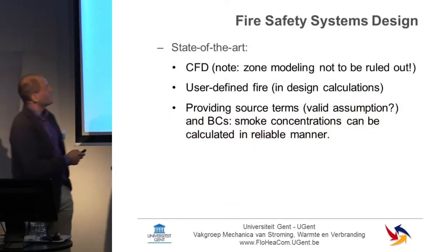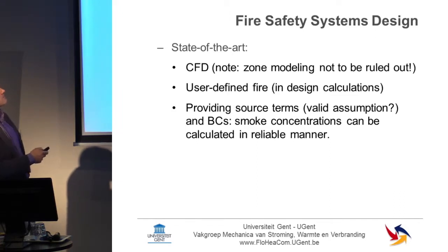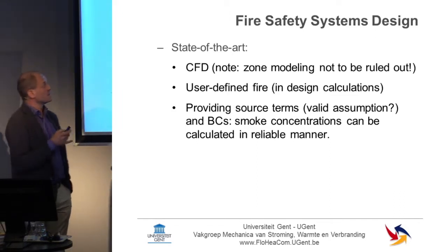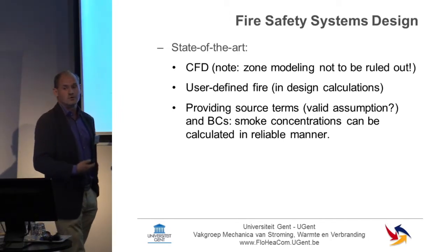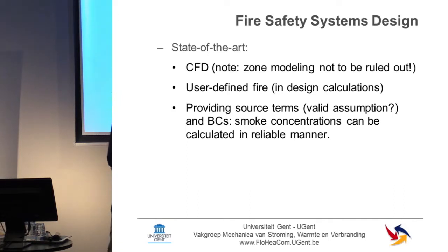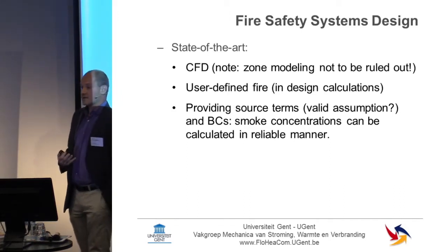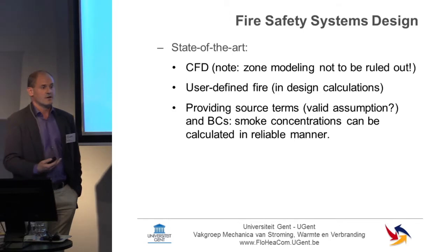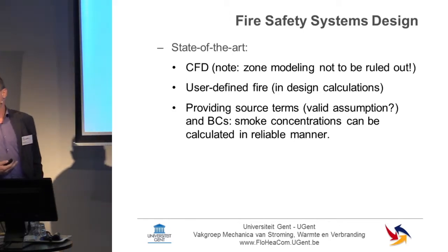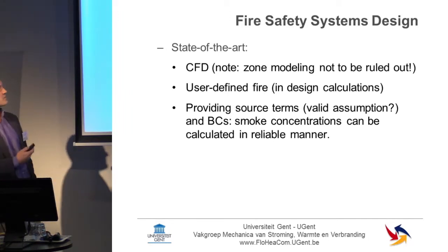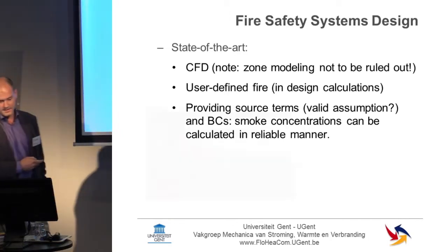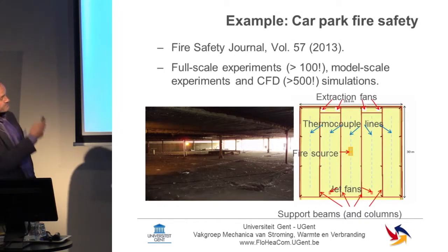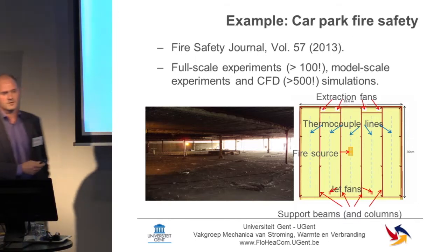So what you get is that these calculations at this point in time are very reliable in terms of smoke concentration, i.e., if you accept beforehand that there's a certain production of soot given a certain combustion capacity. I'm not saying it's a very good assumption, but it is an assumption that is being made quite often. So if you do that, we can count on CFD in the systems design.